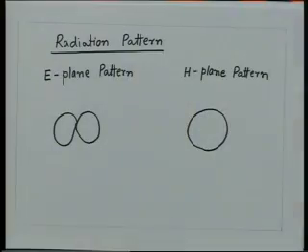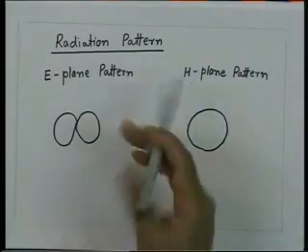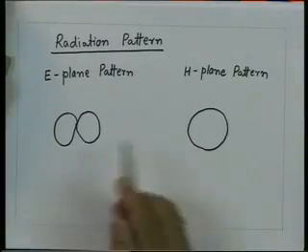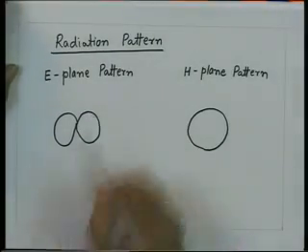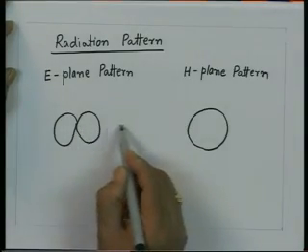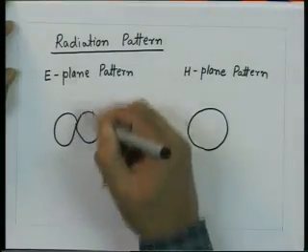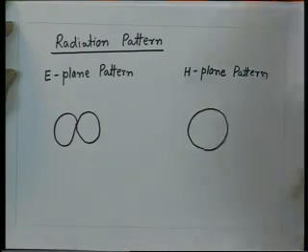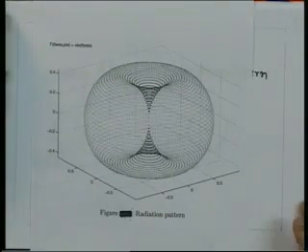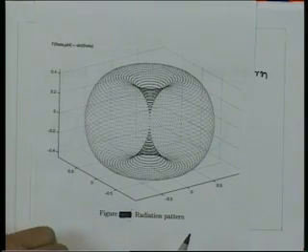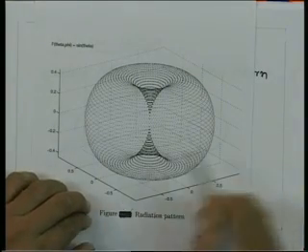So, the radiation pattern is a very important aspect of an antenna, because it tells me in which direction the power is going, and as we saw the power is proportional to mod E square. So, the power is maximally going in this direction, and no power goes in this direction. If I look at this radiation pattern in 3 dimensions now, where is the maximum power going?